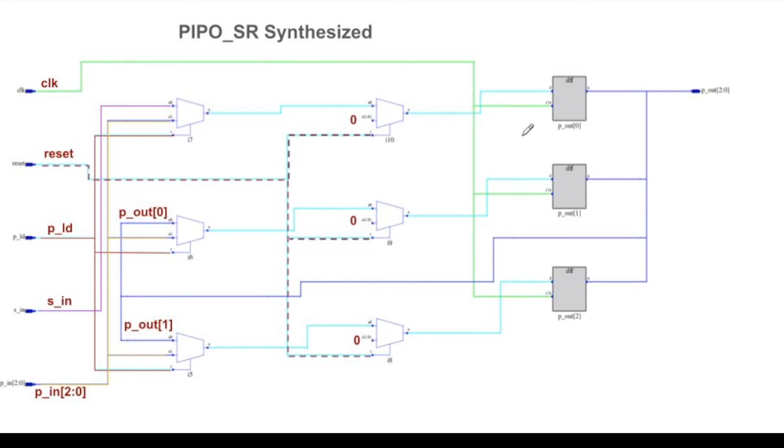They're shifting values from one D flip-flop to the other. So for the shifting pattern that we want to happen, the old value of this D flip-flop has to become the value of this D flip-flop. So how can that happen? Well, this output is going like this and snaking around like that, and then going into the input of this mux, and thus becoming the value of this flip-flop. And then similarly, the output of this one is snaking around like this and going to this mux and becoming the value of this flip-flop. So that's how the shifting happens.